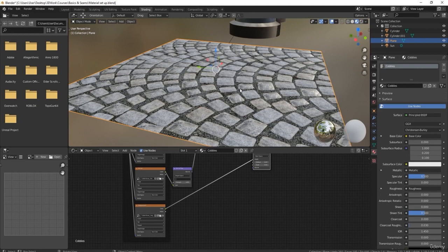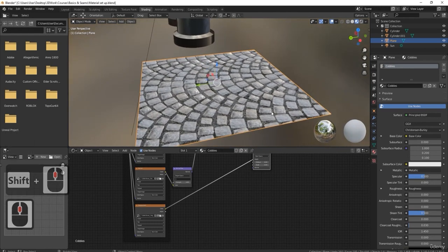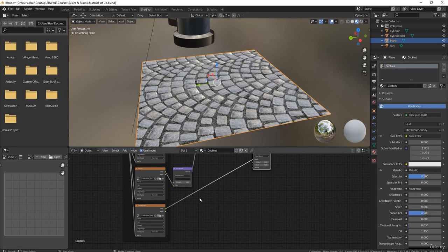If you're using this displacement map, you really need to know two things. First of all, it doesn't work in Eevee. Second of all, it really needs a lot more geometry than what you would normally have. So here we can see we've got a flat plane, and we can see that they're slightly pushed up, and you can still see that this is basically a 3D texture. So how do we create displacement on this?